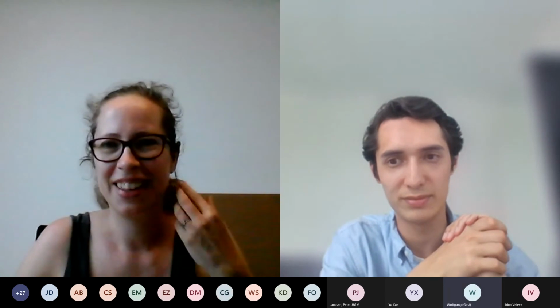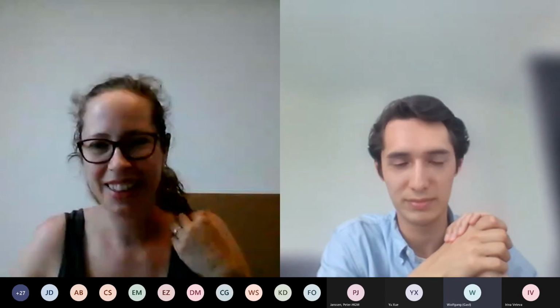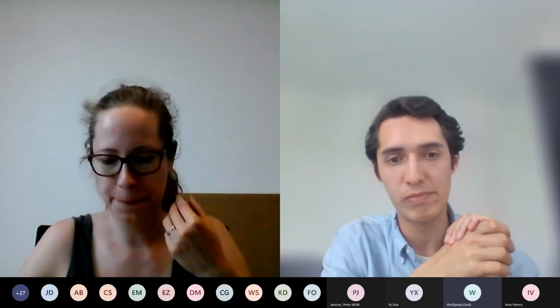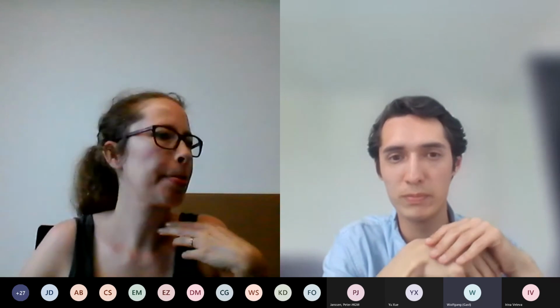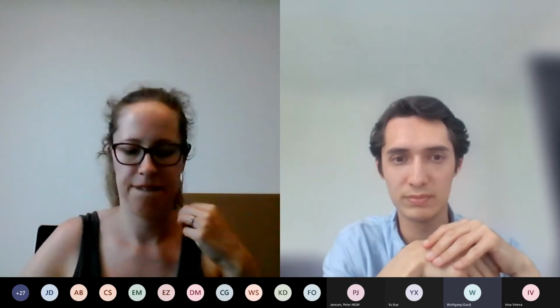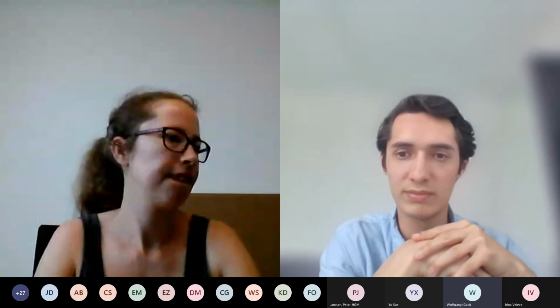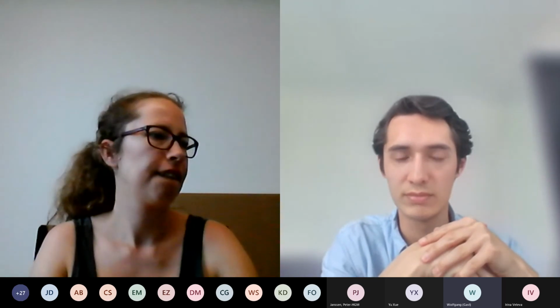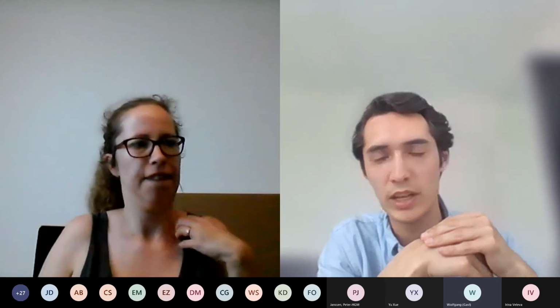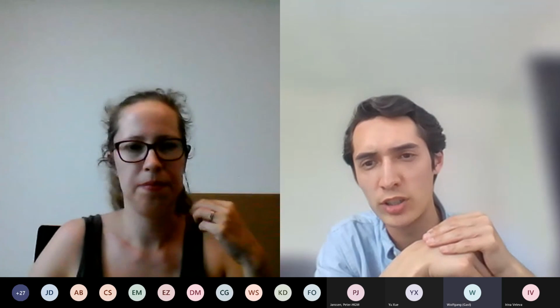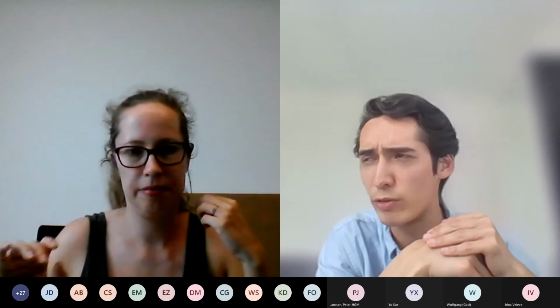Maybe I did not. Can you hear me? Yeah. Okay, maybe I can clarify my question. You determined corrosion by weight loss. Did you use a pickling solution for the determination of the weight loss, or did you just mechanically remove the oxide layer? I used a chemical solution.